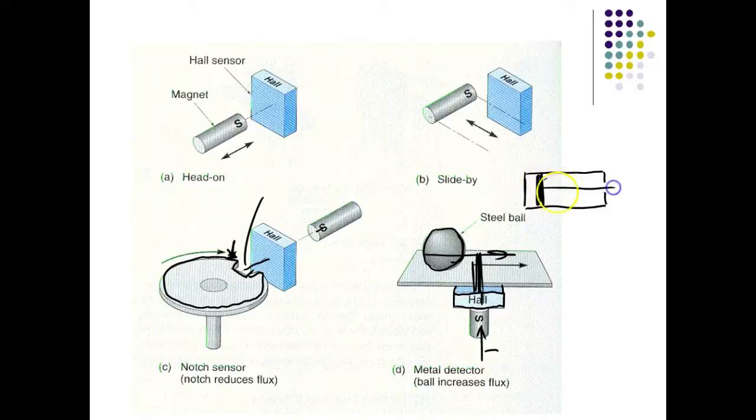And now most of them, a lot of them out here, will have the actual puck inside there with a magnetic ring around the back of it. And then we can put Hall effect sensors up here, and we can sense when the cylinder is extended or retracted. When I get back from Germany, we'll go over to the manufacturing line and look at all the Hall effect sensors that they use to sense when those things are extended and retracted. They use a Hall effect sensor or reed switch.